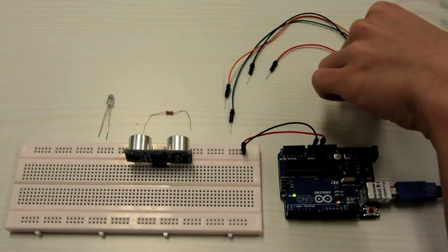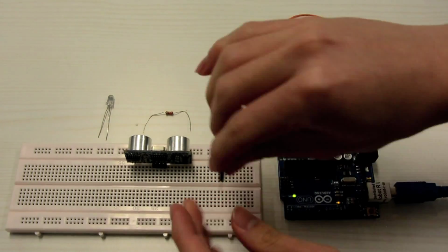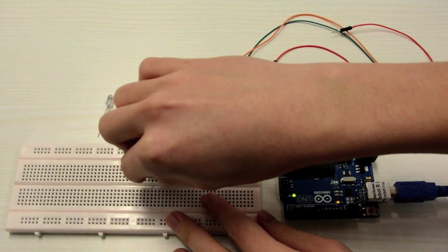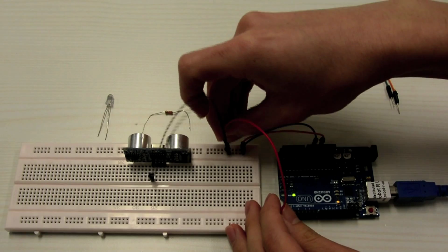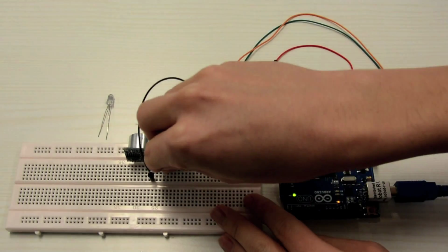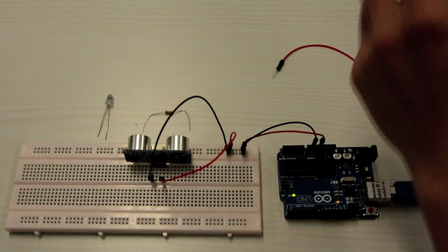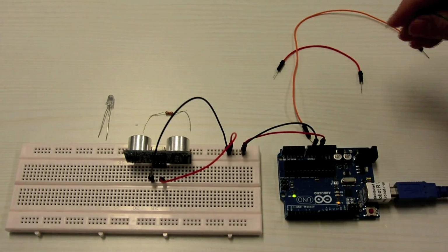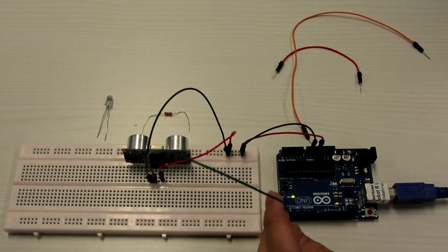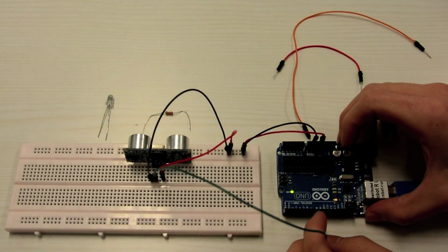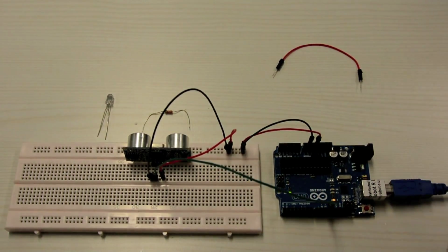Likewise, we need to power this device, and to do that, we first connect the ground from the breadboard to the ground of the ultrasonic sensor. Next, we connect the 5V on the breadboard to the VIN or VCC on the ultrasonic sensor. In order for the ultrasonic sensor to communicate with the Arduino, we need to connect two more pins, the trigger pin and the echo pin. For our code, these will be connected to pin 11 for the echo pin and pin 12 for the trigger pin.